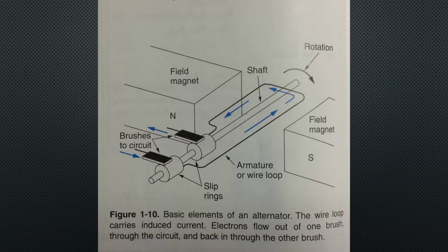Alternators. An AC generator or alternator consists of several parts, figure 1-10. The following is a brief description of 4 basic parts. First, the coil or armature rotates. Its conducting wire cuts across a magnetic field. The electron flow begins in this part. Second, the stationary poles, sometimes called the stator, create a necessary magnetic field. In some generators, the poles are magnetized by a portion of the electrical current generated.